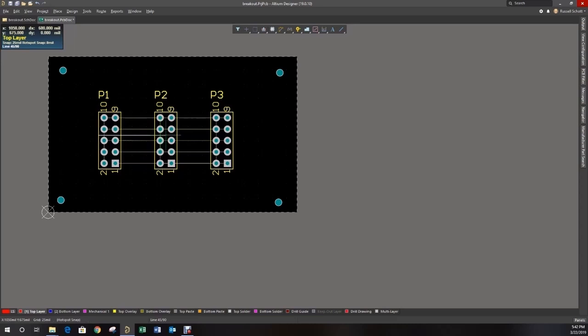And now just sit back and relax, because it takes a little while to navigate through all of the power plane considerations. Once we get the plane defined, you can use the Tab key and edit the parameters for the power plane.